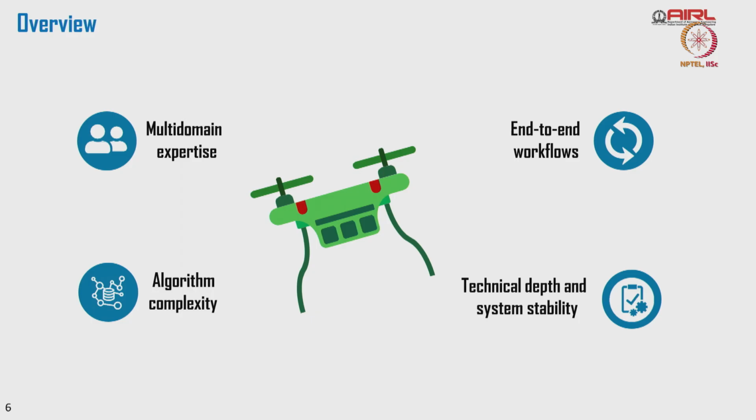Now it's very important to get that kind of flow rate or penetration below the foliage. The drone needs to fly at a different height. If it flies closer, the downwash can damage the plant. So the domain expertise also comes into the picture, not a single domain, multiple domain expertise.